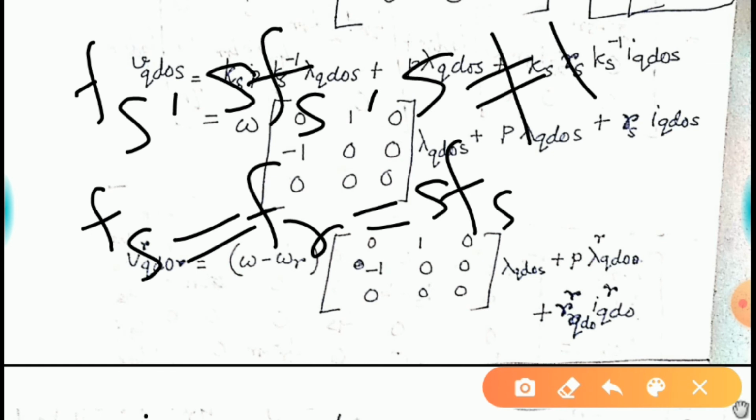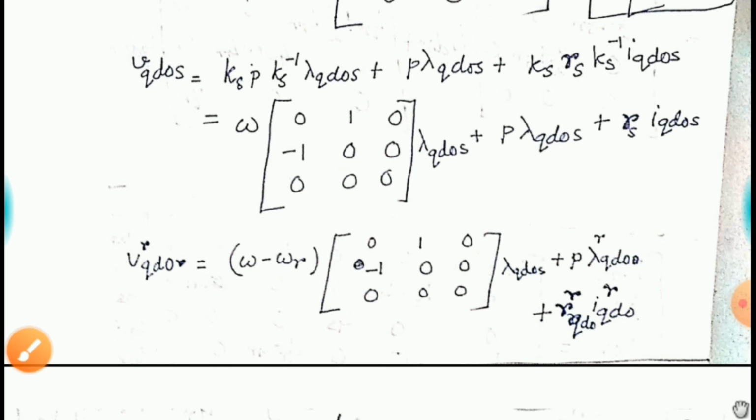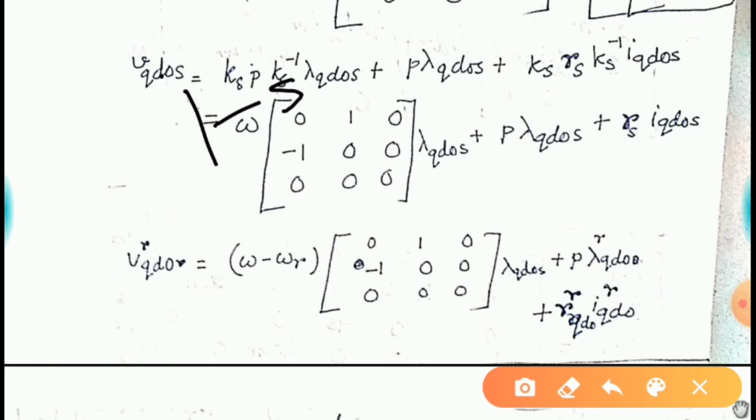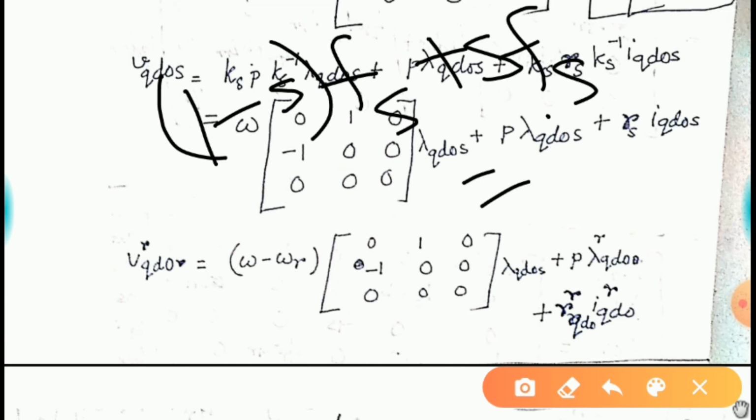Now when we consider the rotor mechanical speed, this Fs is the frequency of the rotating magnetic field produced by your stationary stator winding, and this Fr is the frequency of your rotor winding conductor. But what is the physical speed of your rotor winding? If you convert it to frequency, you will see that the rotor physical speed is 1 minus S times Fs. So when you add 1 minus S times Fs plus SFS, you get Fs.